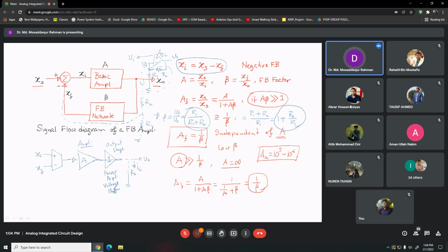induces a lot of noise, right? And a lot of heat dissipation. So usually the current level is kept low unless it is absolutely necessary. Right? So usually this amplification of the voltage is done in the amplifier stage, and then at the output stage, the current level is increased, that can satisfy the current requirement of the load.